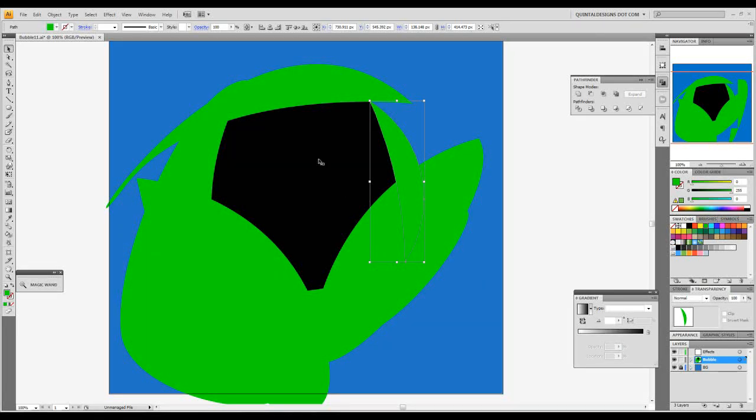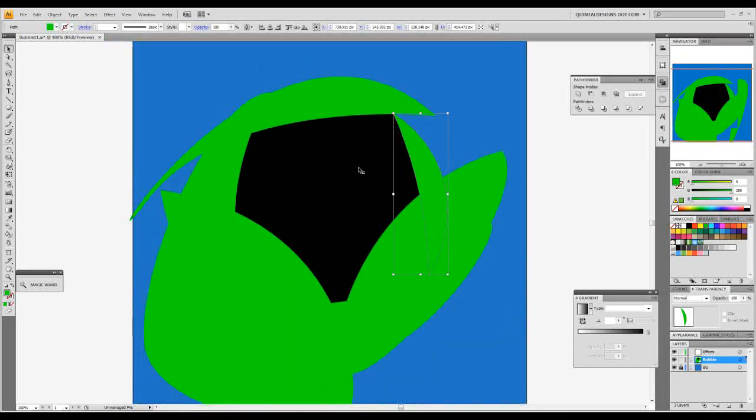And we're going to do it a couple more times so you get used to it when I refer to it. Click on the circle, Alt, right, let go, left, select your second thing with Shift, and then intersect. So Alt, tap, tap, Shift select, intersect. So that's it. That's the double tap.